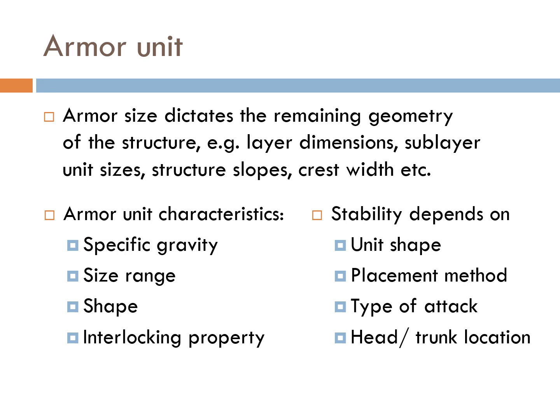Its stability is highly dependent on the shape, the placement method, whether it is arranged or whether it is dumped in place, the type of attack, and also the location of the armor unit, whether it is positioned at the head of the breakwater, which is subjected to more severe conditions, or whether it is placed at the trunk.